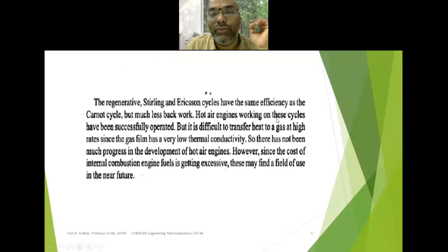Hot air engines working on cycles like the Stirling, Ericsson and Atkinson cycles have been successfully operated, but it is difficult to transfer heat to a gas at high rates, since the gas film has a very low thermal conductivity, because gases have lower thermal conductivity values. That's why it is very difficult to transfer the heat. So there has not been much progress in the development of hot air engines.